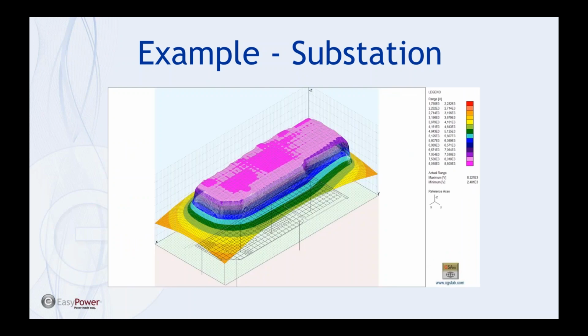This visual shows the ground potential rise with the proposed grid design. This is during the design fault that we've applied, with the soil model applied to the preliminary grid design shown below. You can see the grid and some ground rods going down in the Z direction from the grid. This is a nice visual because you can see that the grid area, the elevated area in pink on the GPR chart, is brought together up onto an equipotential plane.